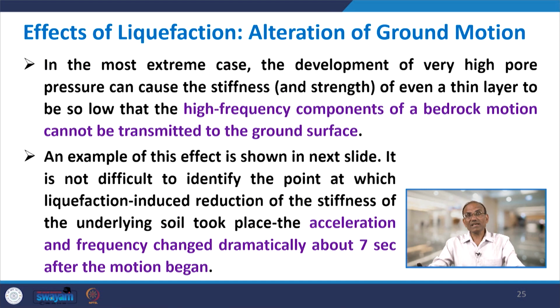In the most extreme case, very high pore pressure can cause the stiffness and strength of even a thin layer to be so low that the high frequency component of a bedrock motion cannot be transmitted to the ground surface.